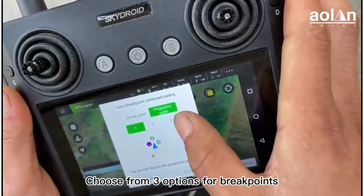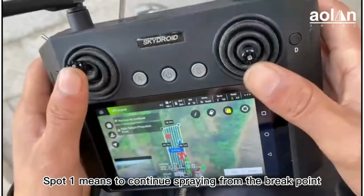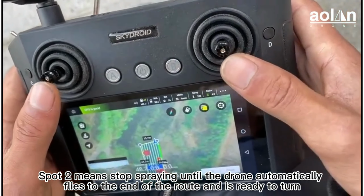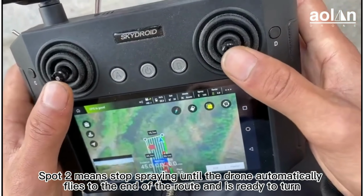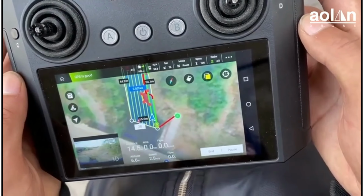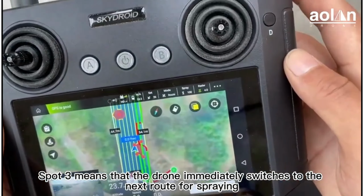Choose from 3 options for breakpoints. Spot 1 means to continue spraying from the breakpoint. Spot 2 means stop spraying until the drone automatically flies to the end of the route and is ready to turn. Spot 3 means that the drone immediately switches to the next route for spraying.